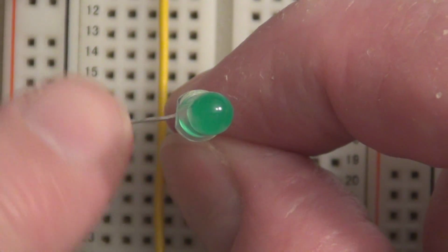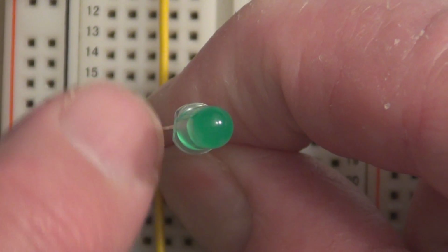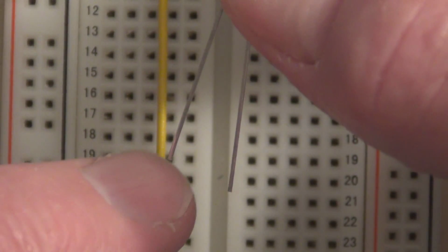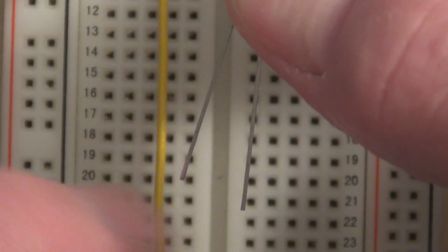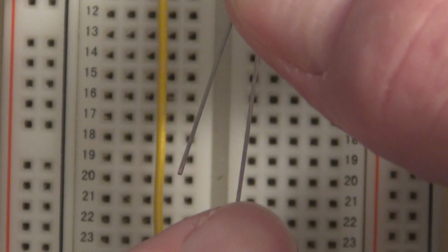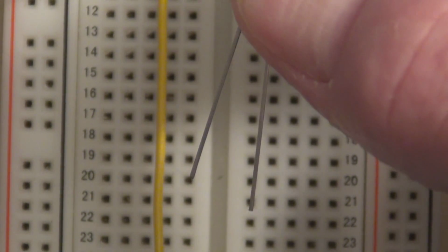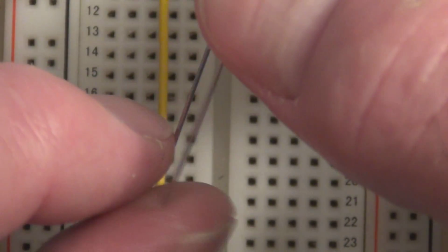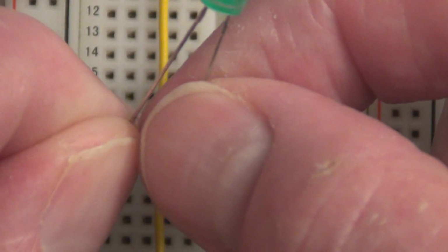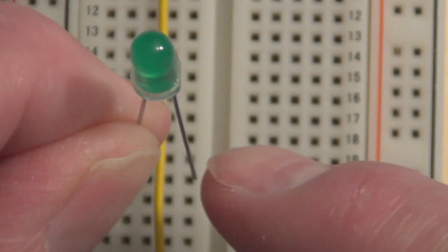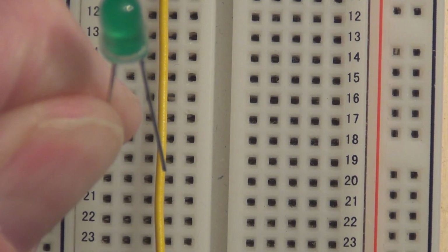That's more discernible right there. That line indicates how you want to orient this. And if you haven't previously cut these leads, the shorter lead is the cathode. So the anode you want facing toward the digital pins that you're going to designate in the program, because you're going to make that either go high or low, and if it's high, then this LED will turn on. The cathode, or the shorter lead, is pointing toward the ground through the resistor.